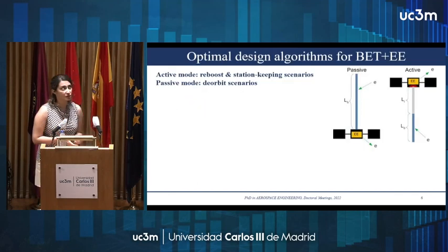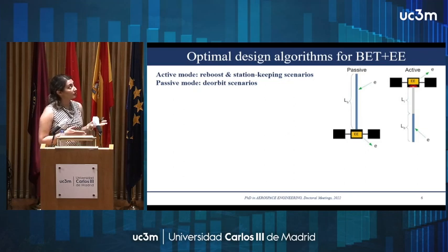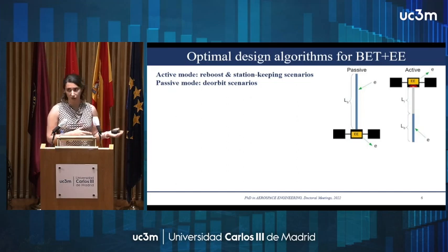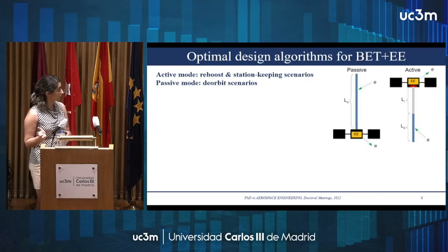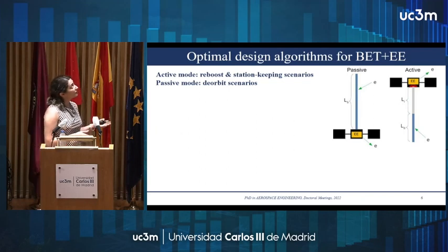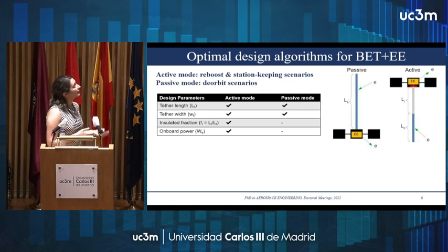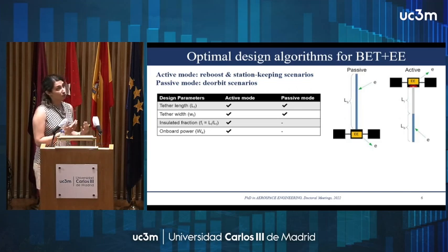So we proposed an optimal design algorithm for bare electrodynamic tethers equipped with an electron emitter, considering some mission requirements and some figures of merit. It covers both active mode and passive mode. In active mode, we also have onboard power.